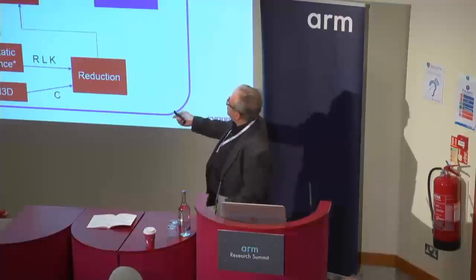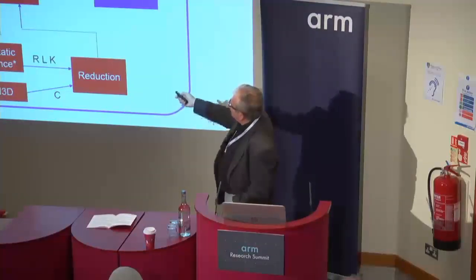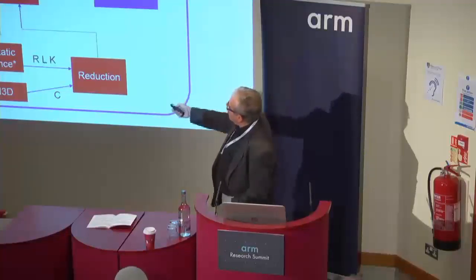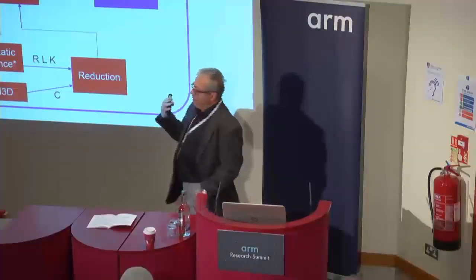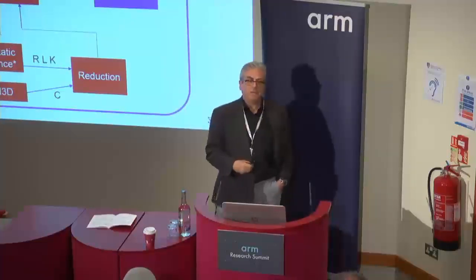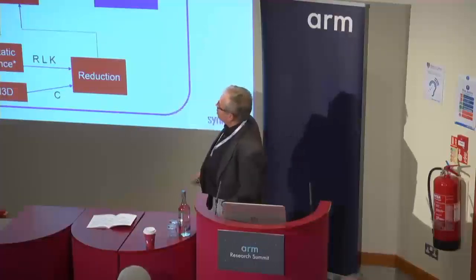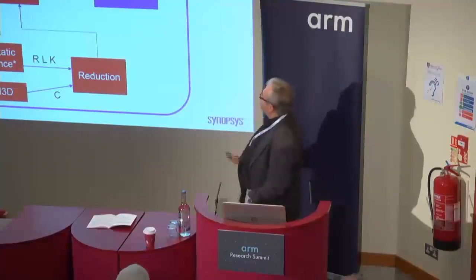So the target is to be able to do RLC, kinetic inductance as well as Josephson junction device extraction, all based on lookup tables within a 5% accuracy from field solver. This is our target for the chip level extraction.